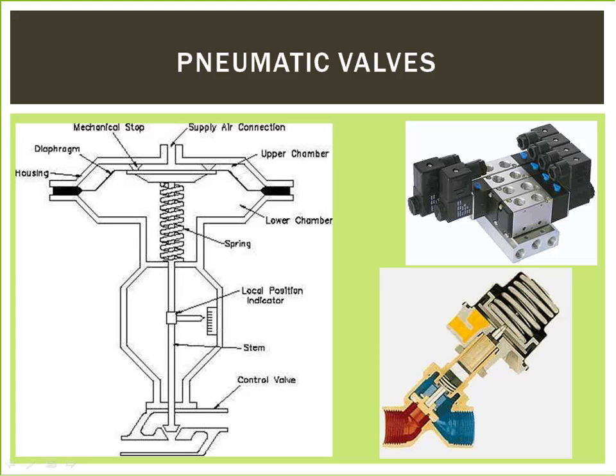A two-way directional valve passes air in two directions, through two ports which can be open or closed. A three-way directional valve has three ports, each of which serves a different purpose. The first port is used to connect the valve to an actuator or another device. The second port is connected to an airflow, and the third port is used as an exhaust exit.